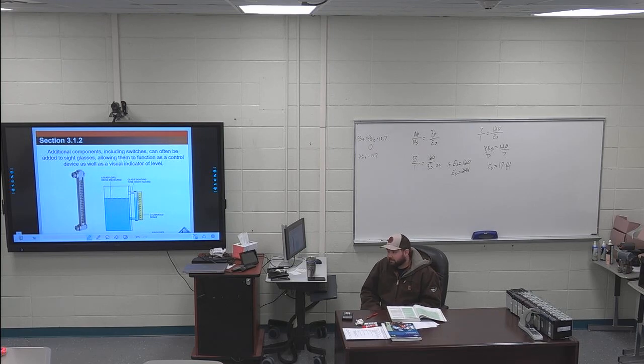Another one would be like the dipstick in your car. You're measuring the level directly, essentially. Sight glasses are another way to measure directly. For y'all that have been working on the trainer right here out the door, there's a ruler or whatever on the outside of those level tanks. That's measuring it directly. Whenever you're supposed to keep it to like 5 inches, that's measuring it directly.